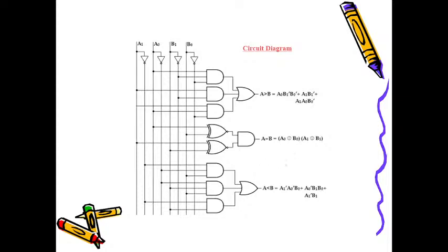This you know. Okay. For the equality function, 2 XNOR gates, because 2 bits: A naught, A1, B naught, B1. So A naught, B naught for one XNOR and A1, B1 for the next. It will compare. Only when both the bits are equal, you will have the output high. So that is why an AND gate. This bit has to be equal and this bit has to be equal. Look at the word I am making use of: AND.